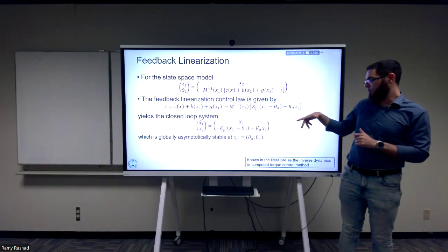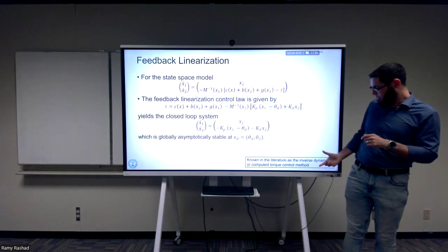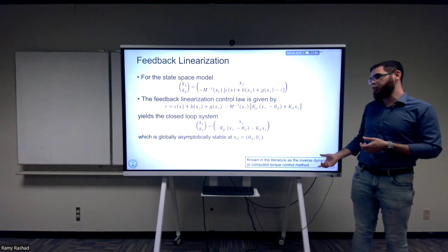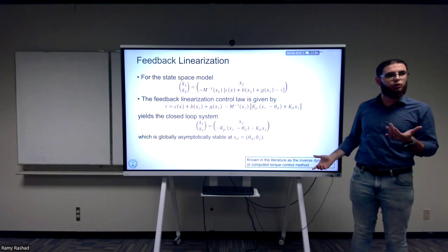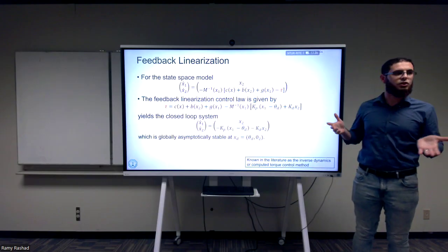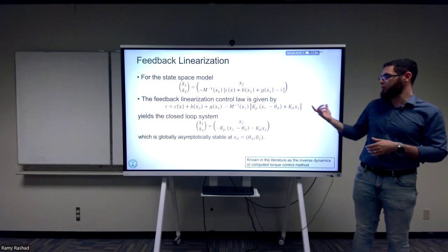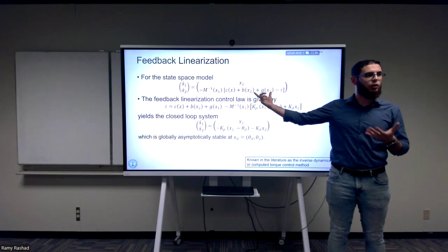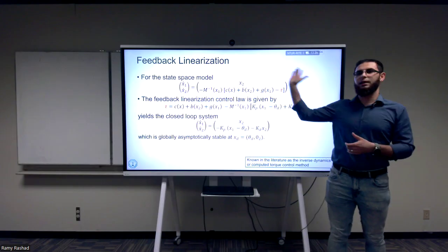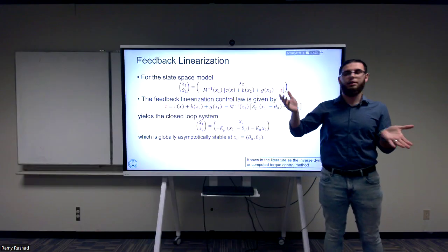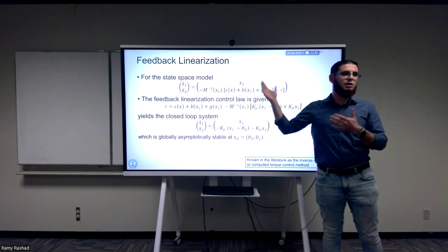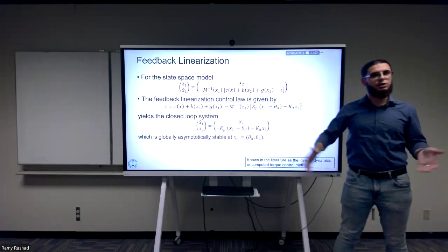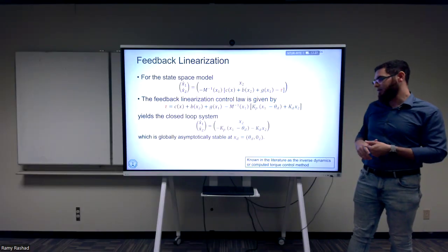What do you think the problem of this is? And just another point, this is usually in the robotics community known as the computed torque method. It's the computed torque method, and in other literature it's just called inverse dynamics control. And you see why? Because we're inverting the whole dynamics. I have the dynamics of the system, I know it through modeling, and I'm just killing all of it. I'm just inverting all of the dynamics. Whatever was plus is minus. Whatever is multiplied, I just multiply by its inverse and so on. So I'm just inverting all of the dynamics that I have in the system.